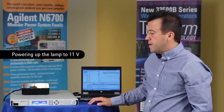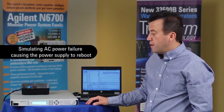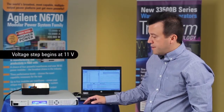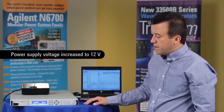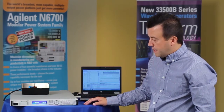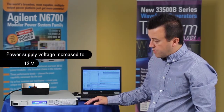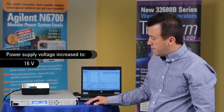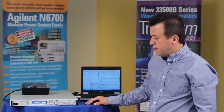So we're now powering up the lamp. We now just emulated an AC power failure where the instrument is actually rebooting. I now started stepping the voltage. Now I'm incrementing the voltage to another level, and as you could see, the intensity of the light bulb changed. And you could see there is obviously a voltage step change, plus also your current is getting increased. Now the test has completed, and the output of the power supply is off.